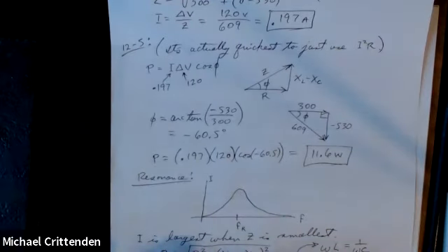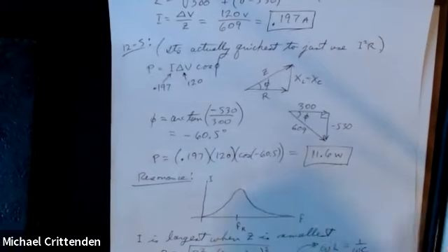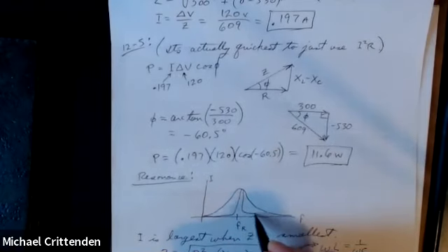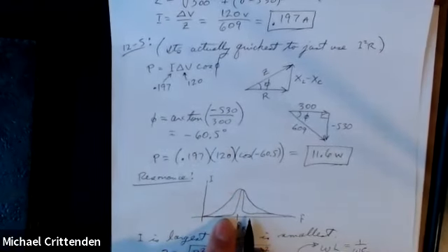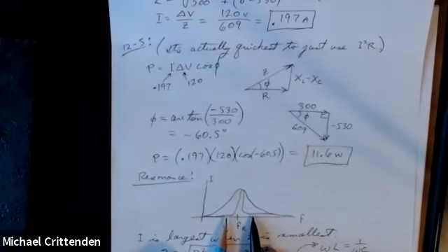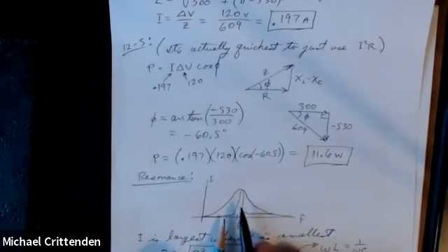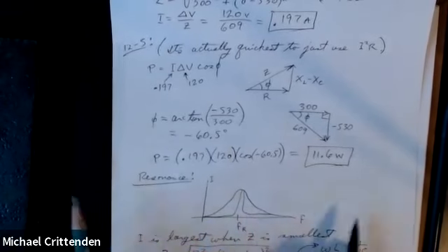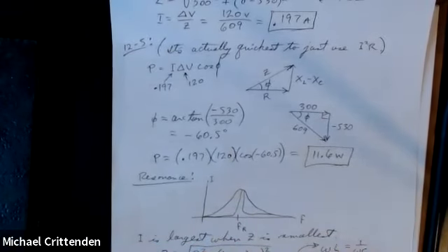Anyhow, you want to pick values in your circuit so that you actually have a nice narrow peak, something that looks a lot more like that. And then you see the closest stations, aside from the one you want to hear, are there and there. So the station you want to listen to has a large amplitude, and all the others get filtered out enough that you can't hear them in the background. So anyhow, that's the story of how that's done. That's the background behind example number 6.